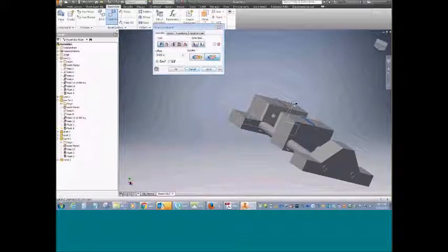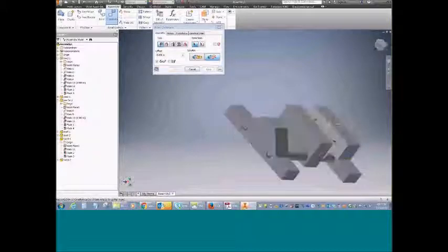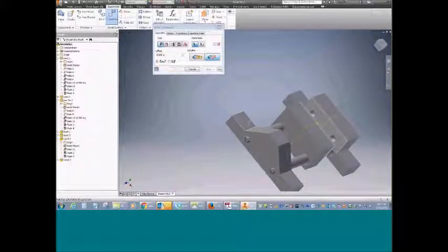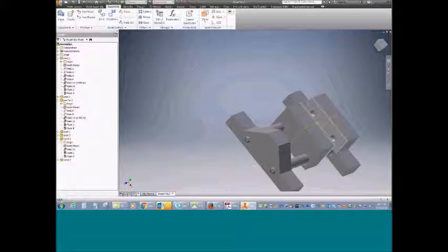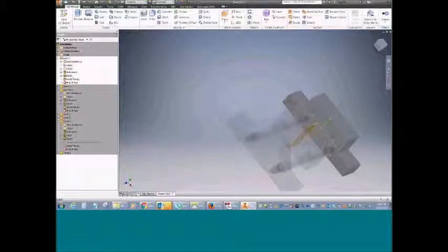There we go. So those mid-planes will keep my jaw plate centered. And I encourage this because now this will comply with design changes, that if we make something longer or edit the size of different parts, I get some design intent going here. And then as we talked about, for these holes in these parts right here, I'll just edit those in place now that I have my jaw plates at their location. So I'll go in and edit that one.